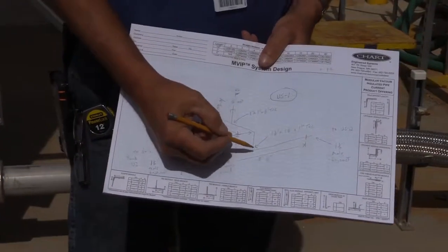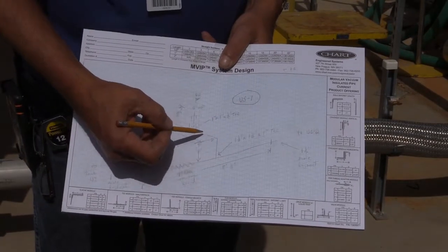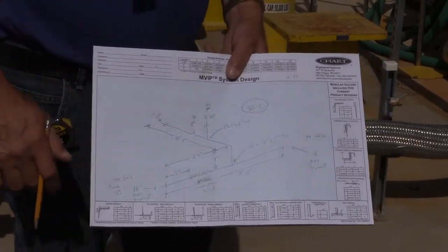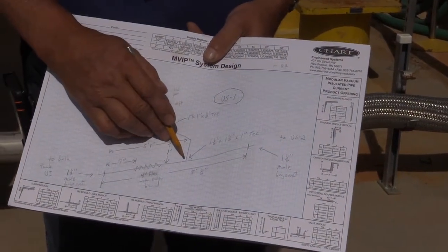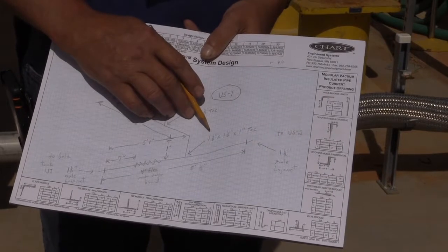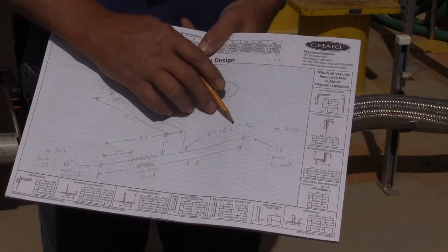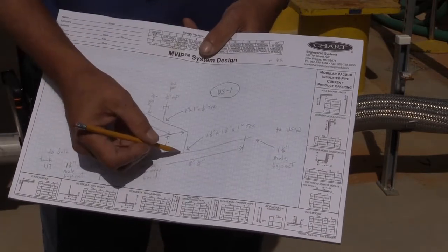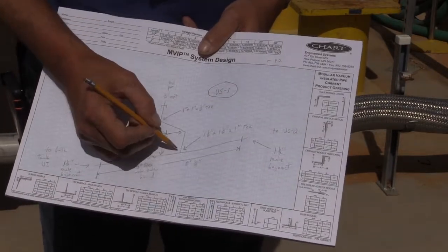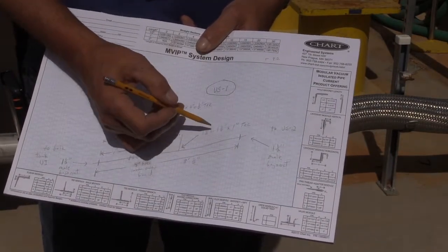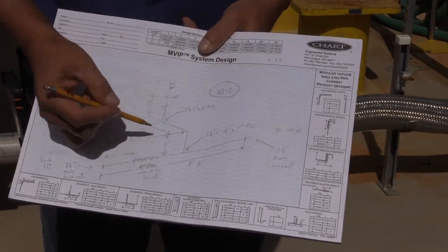Then you'll see that we make some direction changes where we go up and over for an auxiliary line. Critically important that when that's done, you label what that T section is. You'll see on this one I've labeled it 1 1/2 inch by 1 1/2 inch by 1 inch T. So they know that this is a pipe size change, that the header is 1 1/2 inch, and that once we begin the rise up here, we reduce that down to a 1 inch section.